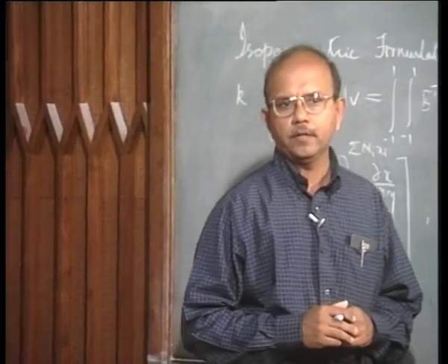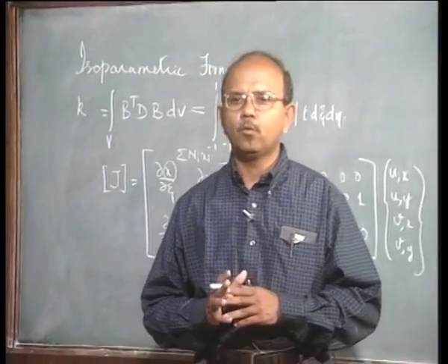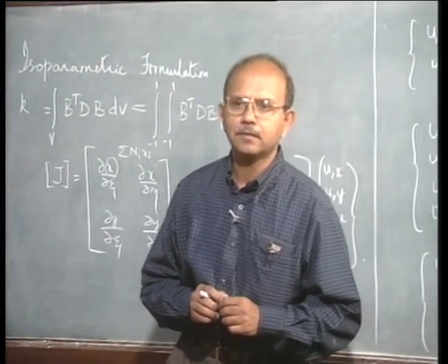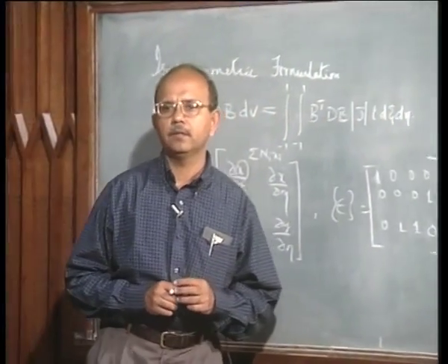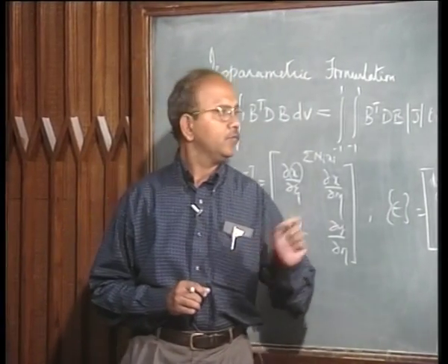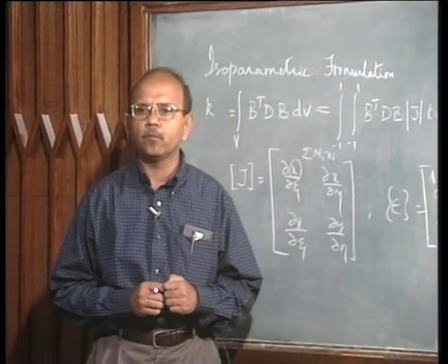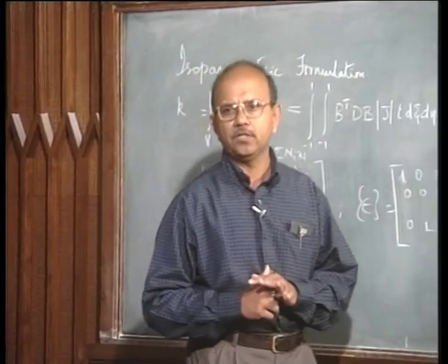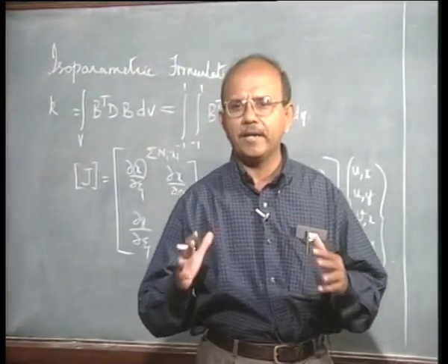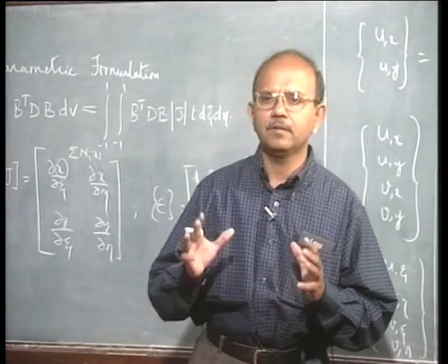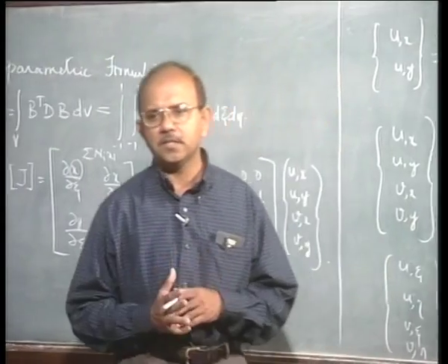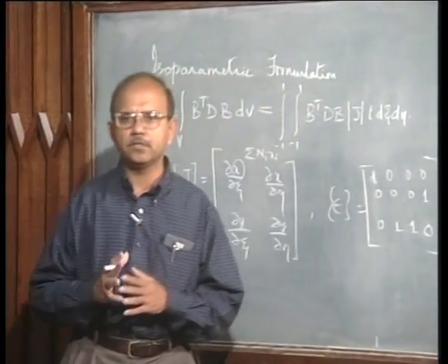Before we go further, let us summarize what all we did in the last class about isoparametric formulation. Remember that we talked about isoparametric formulation as a very general methodology for a variety of elements. The elements may be plane stress, plane strain, solid elements and so on.